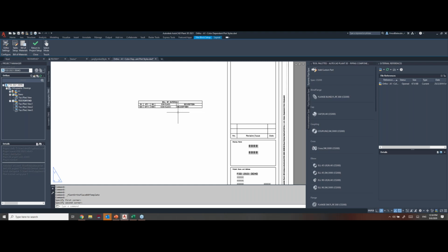You don't need to do that during the time of ortho creation or after. You can place your BOM table where it needs to be, and then save it to the template. Later, when you generate your ortho, the bill of materials gets updated for the model that you're generating the ortho for, and the location of your table will be retained where you put it in your template.